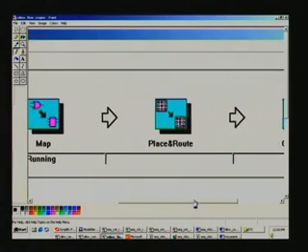And this is a laborious process, place and route. What we have done is select the device, and then within the device, it has placed all the primitive cells. Actual placing happens only here, and it places all the primitive cells at strategic points, considering what is best in terms of the frequency of operation that you may get. It always has an eye on the frequency of operation, and once it is placed, it starts the routing.